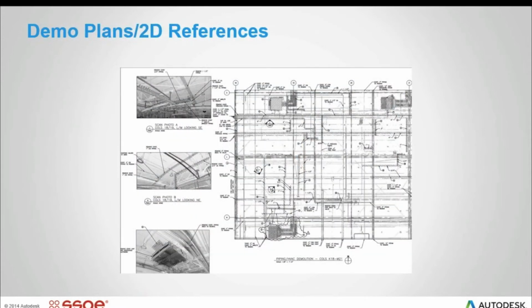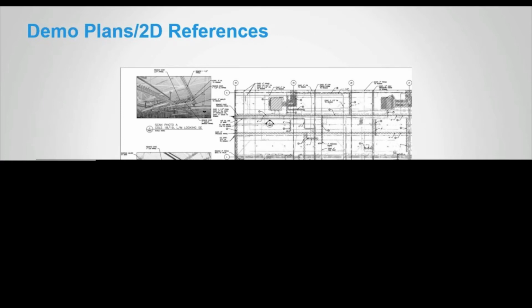So a workflow that we talk about is demolition of point clouds. This is actually what was issued on a project. We took 3D views along the left-hand side from ReCap. We saved them as a JPEG, annotated them in Revit, and took a straight orthographic view of the point cloud, because when you flip your 2D plans, it turns into orthographic. That is a point cloud that is referenced directly into the sheet with annotations for demolition.